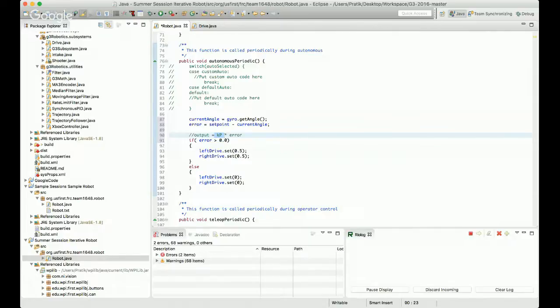If it spins at full speed for maybe 90 degrees and then starts slowing down, it can probably reach 180 degrees fine. So for that, we want this to be 1 over 90, because that means when Kp is 1 over 90 and error is 90, the output will be 1. And any value higher than that for error will do less and less.